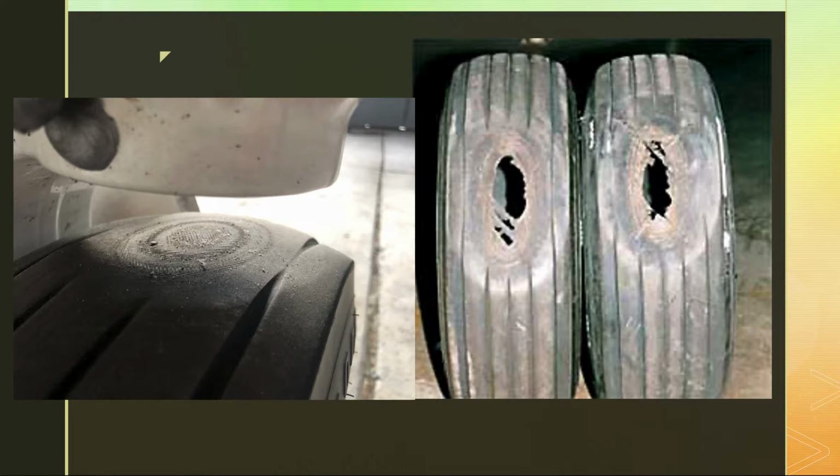All right, this is what happens all too often when pilots use the brakes improperly. These things don't have anti-lock brakes. They generally will not have anti-skid brakes. If you push the brakes too hard, they lock up, and they only unlock if you let go. And it's really hard for your flight instructor to get you to get off the brakes, because I can't unclench your thighs that you're trying to push the pedals through the firewall with.